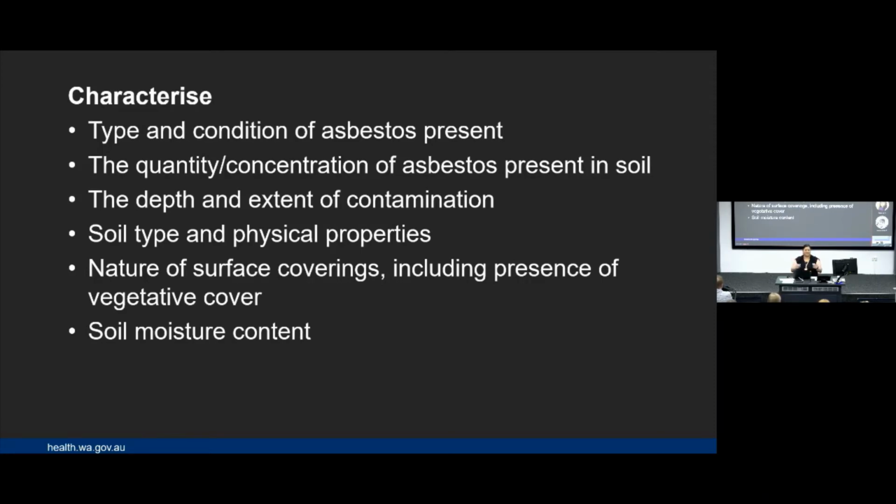So if you're examining surface soils, examine the disturbed soil surface layer where material can have moved through activities happening at that site. That's how we want you to look at that. In some cases, you might have really hard compact soil and you're really only dealing with what you can see on top. You don't actually have to look deeper down if it's really compact soil.